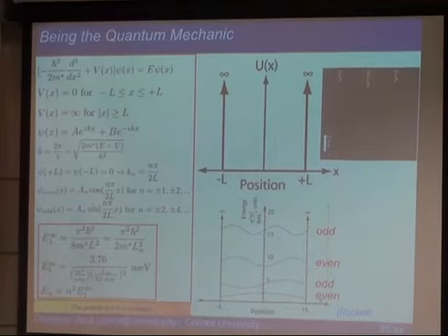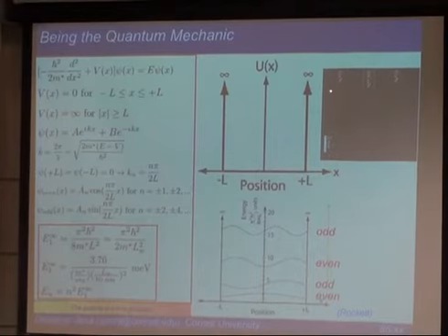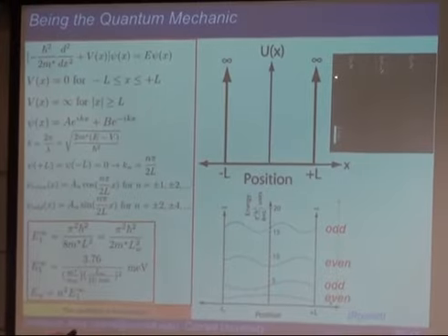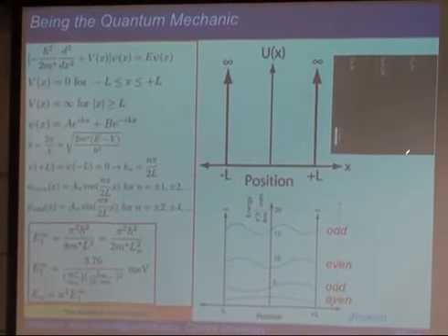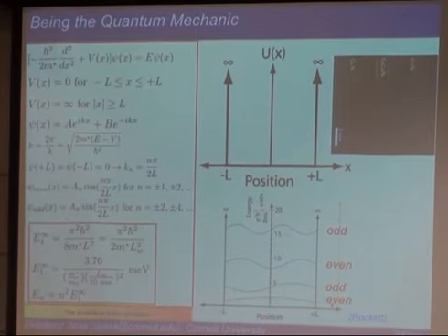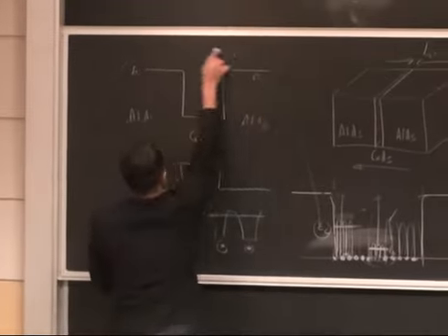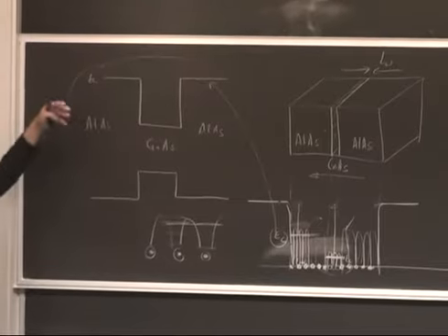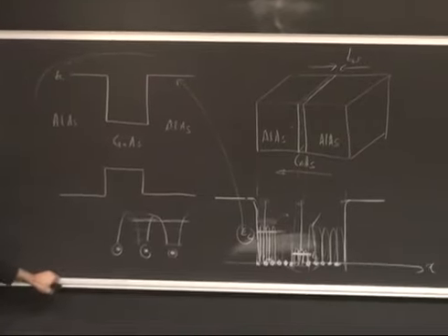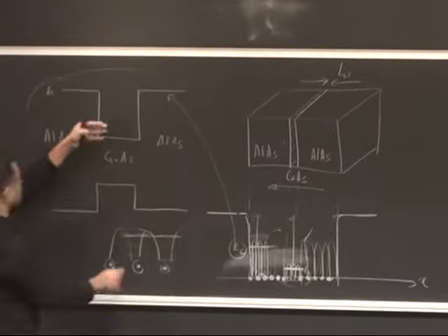So here's the question. We have gallium arsenide, gallium nitride, indium gallium nitride, and gallium nitride. Let's say any quantum well like that. The question now is, what are the energies allowed for the electrons in the quantum well, or in the whole structure, not just in the well? What are the new energies that are allowed? What we are going to start with is to look at just the conduction band edge initially, and ask what energies are allowed here. And you can see it looks like a potential well.